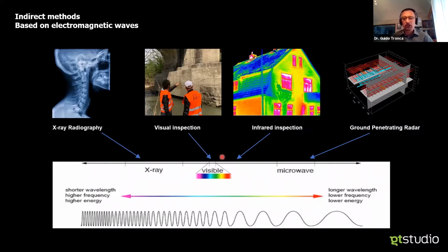A good inspector keeps his eyes open. You have to really provide a subjective judgment on a location. Well, if I shift myself from the very narrow window of wavelength that my eye allows, I can shift toward X-ray analysis or lower frequencies. I will enjoy thermal camera and infrared inspection, or even lower frequency with GPR. All have in common this basic principle.